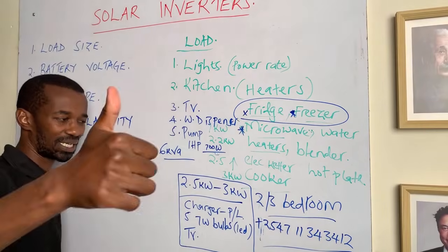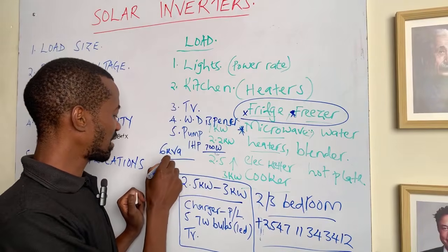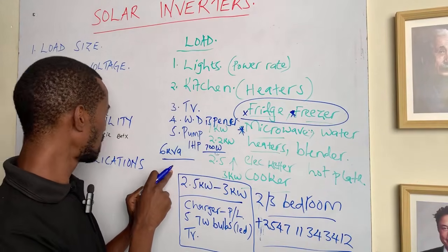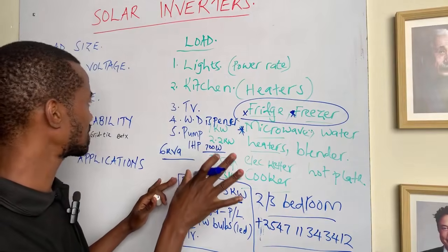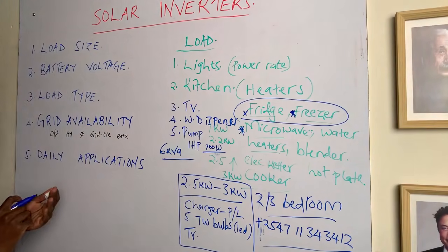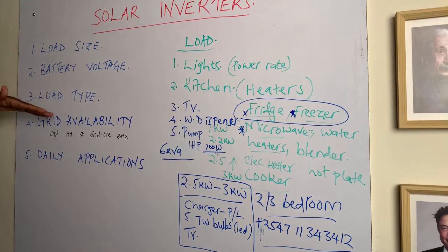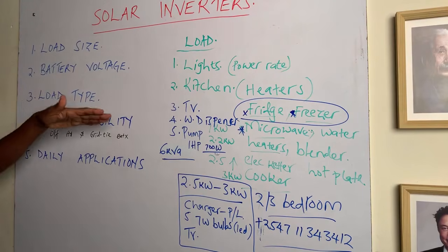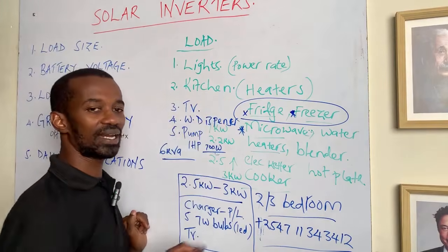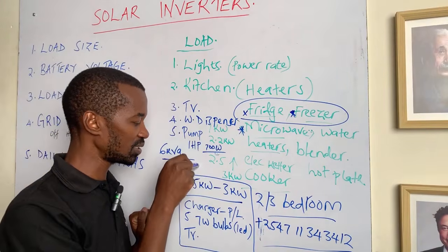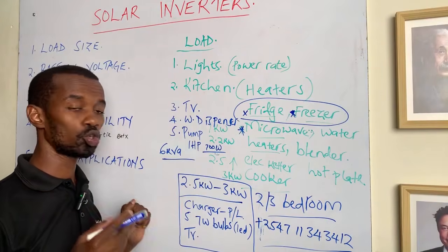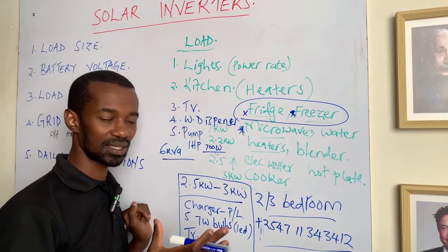So moving on, a 6 kVA system or a 6 kilowatt inverter will definitely work well for this system. Now, assuming it is an off-grid, before we go to the grid availability, we need to mention also that if it is a grid-tied, or an off-grid, or a hybrid system, it will also dictate the number of panels that you require.